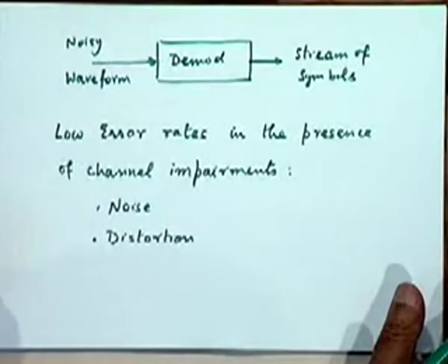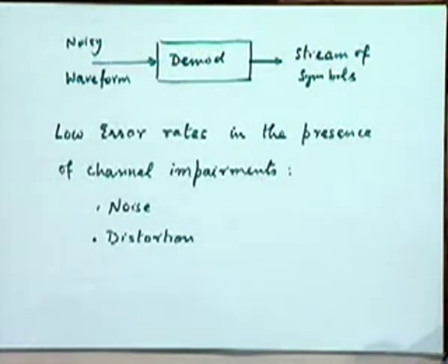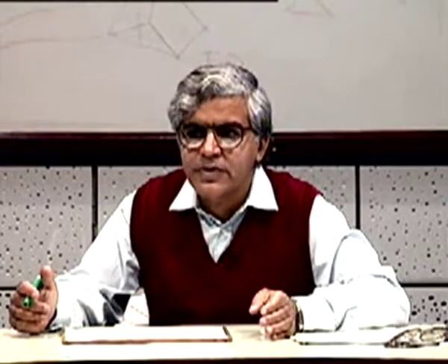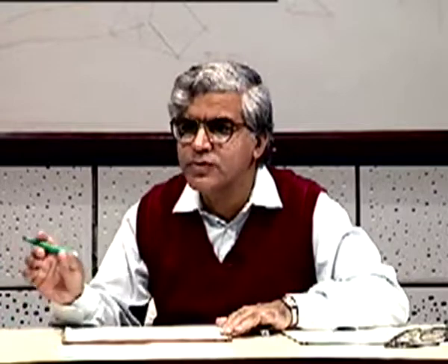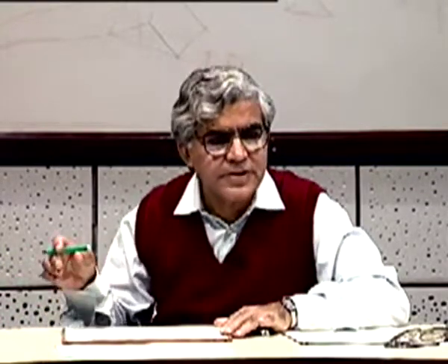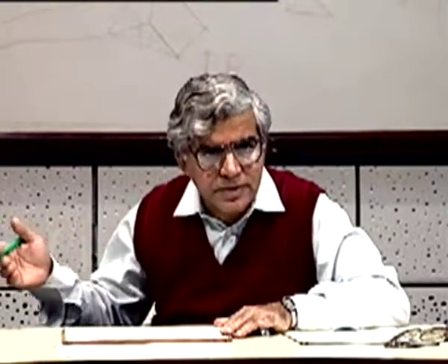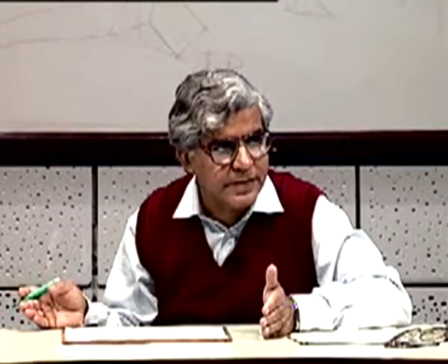Amplitude distortion is caused by the fact that in the bandwidth of interest the channel does not have a flat frequency response. All right. Phase distortion is caused when you have a nonlinear phase with respect to frequency. If you have a linear phase, that will imply a constant delay of the input waveform to the channel output, right? If you have a nonlinear phase response, different frequency components are delayed by different amounts, and therefore the resulting output waveform is not the same as the input waveform.